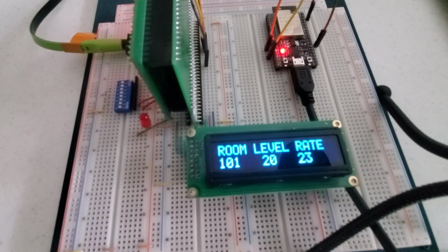Ideally, the nurse's station would command the patient rooms to send it data, and the patient rooms would send their data through the mesh network. Once it had been transmitted and received wirelessly, the ESP32 would send the data directly to the STM32 through a wired SPI line.